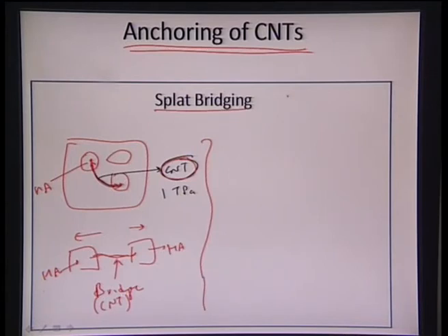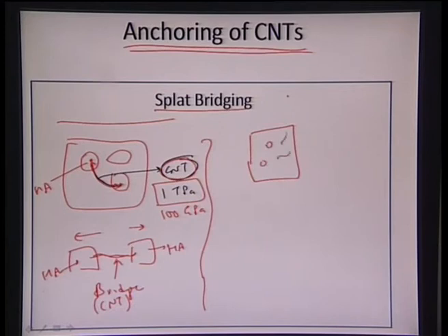Because the modulus is also very high for CNT, and compressive strength is also approximately 100 gigapascals for the CNT. So that particular toughening is being given by the CNT. Additionally, CNTs can also serve as a crack deflection part. So if we had some CNT somewhere, and a crack is flowing, once it encounters a CNT, it will get deflected. Because of its higher mechanical properties, CNTs won't allow the crack to proceed further.